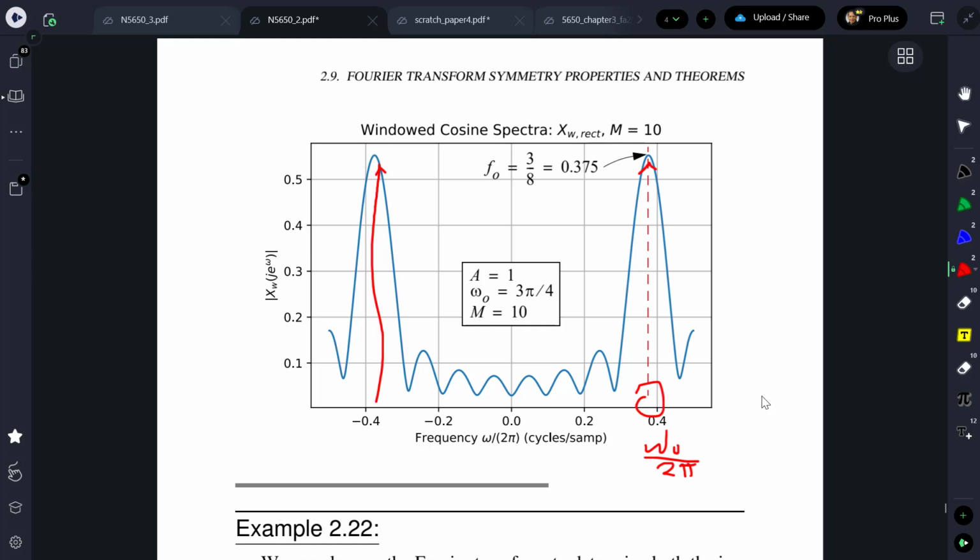So you'd look at that, and what I want you to first notice is that it looks actually pretty good. If you were trying to estimate the frequency, you could use some peak finding function, which is available in NumPy. find_peaks is the name of the function, and you'd be able to find where that peak is. You will have it in the first project, so you will be getting to use that function later. You'd be able to find that frequency pretty accurately, because right now there are no other signals in there to clutter things up. Agreed that that would work? With only 10 points, it's actually pretty amazing.